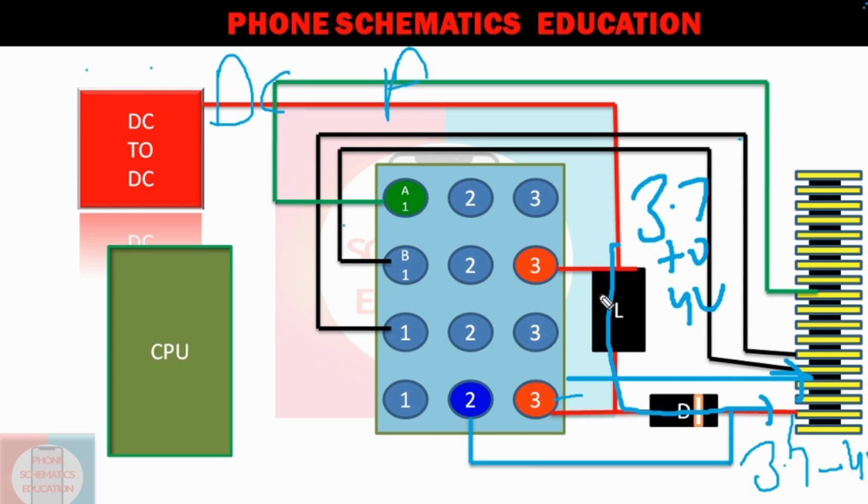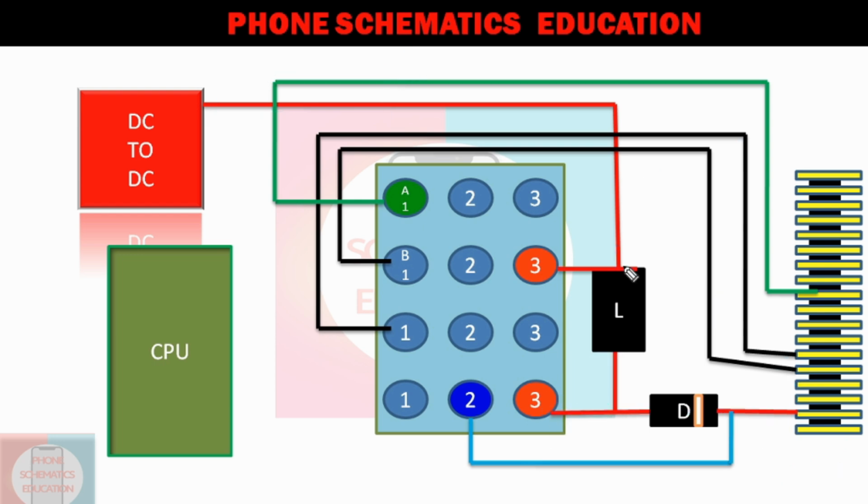Maybe a problem in the switching side, right? Maybe a problem in a diode, maybe a problem in a coil, maybe this IC could not switch properly, maybe no connectivity between this D3 pin and this coil, because you can see the reading, a diode value or a VSYSTEM line.